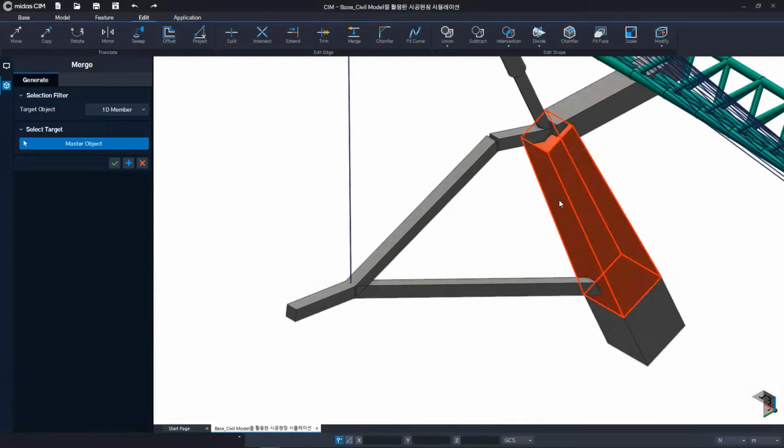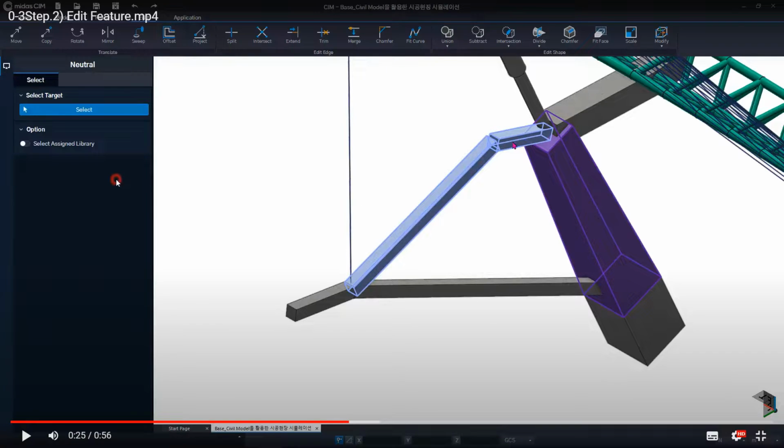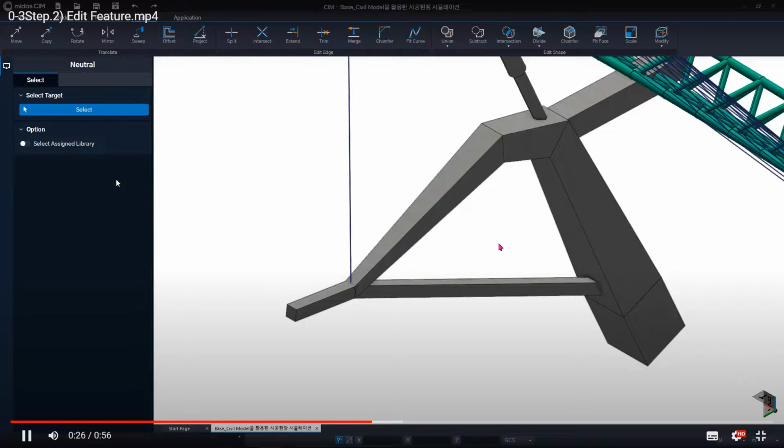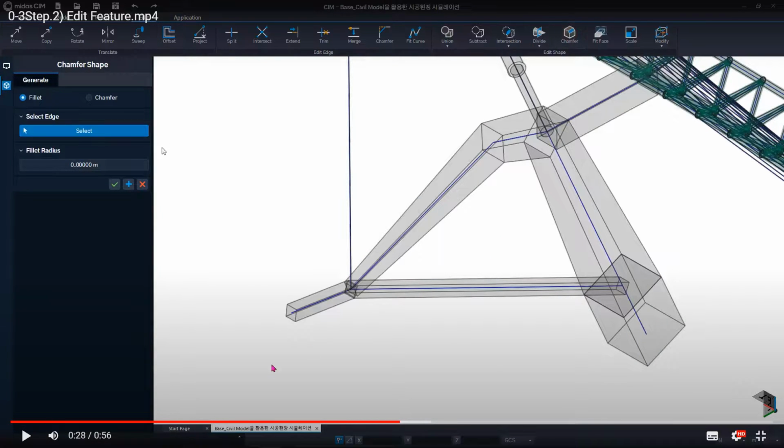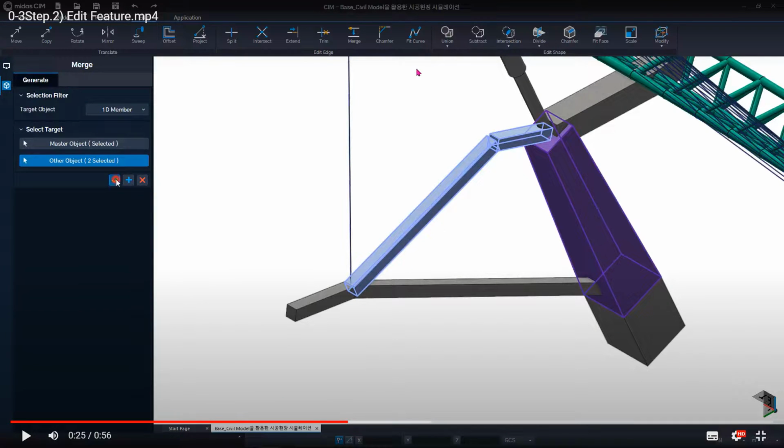You can see here, you click on the master object, and then immediately you can click on the other object. The way to click on both other objects is just you press control and click two of the objects, so it's similar as if you click two files in your Windows Explorer. You can click many files using control and select, and it immediately does that. And you can also see here there are divide, there are also chamfered.